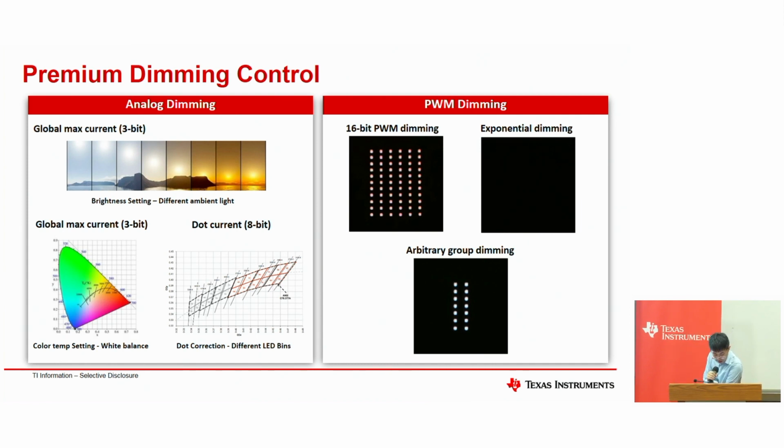The color temperature setting is the second one we are controlling regarding the CIE 1931 color legend graph. This is more for a very professional way of designing the RGB color, where you want to maintain the same color temperature when the LEDs are used for a very long time. If you're using the LEDs for 5 or 10 years, the LED itself can become yellowish after a long time of use. Well, you can use this type of register to adjust the color balance and the temperature.